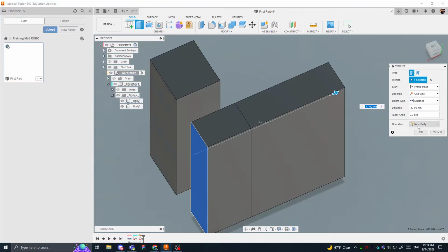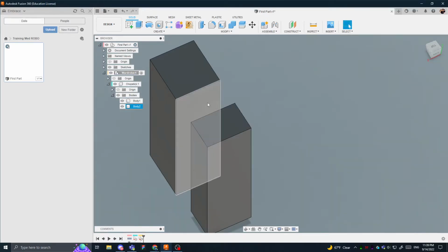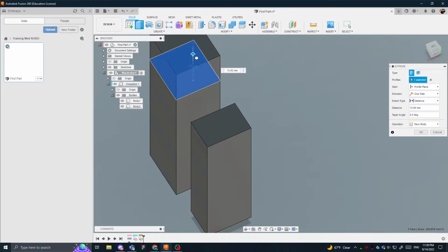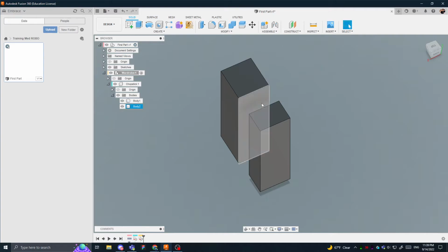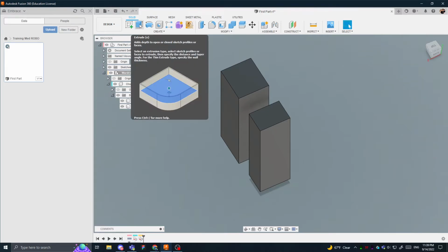So usually you just reselect from here and extrude that much rather than, you know, intersecting 2 pieces. The next thing I want to say is with extrusions, that's your main primary tool of creating things. If you want to pull things up or down and stuff like that, you can with the extrude button right here. I have mine bound to the shortcut E on the keyboard, as you can see in the parentheses there at the top of the description.